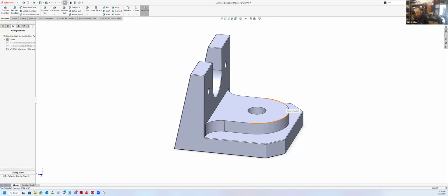And if you use the chamfer function, at least in my software, then it will avoid corners where it would crash into something. So in my situation, I would have to go back and do a sketch line to run the chamfer around. And if you've already got it modeled into the part and you don't send me a file that I can suppress the chamfer on, if I was going to deburr it on the machine.